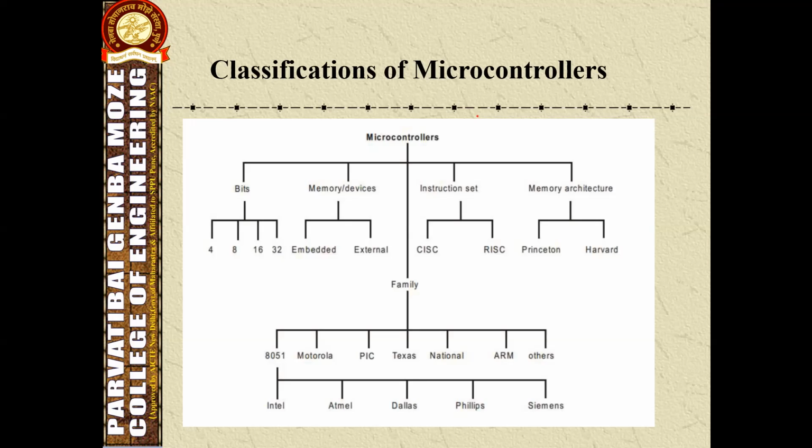The 8751 type of microcontroller has 4 kilobyte of on-chip ROM, and that memory is UV-EPROM. If this chip is to be used for development purposes, then a PROM burner and a UV-EPROM eraser are required. As it has on-chip UV-EPROM, it requires approximately 20 minutes to erase the 8751 before it can be reprogrammed.